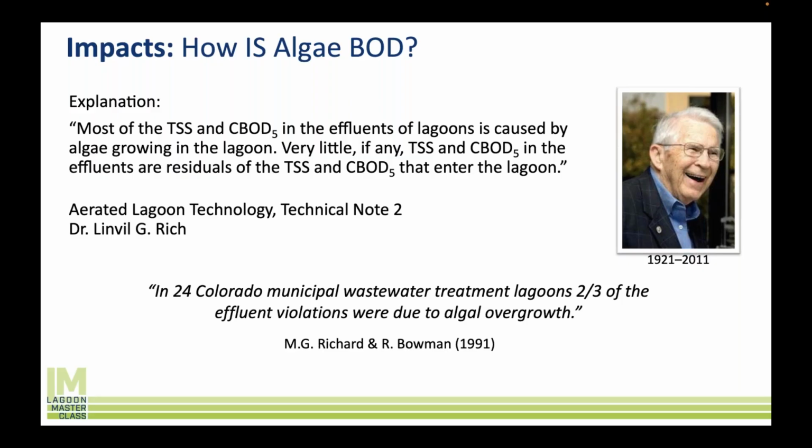So Dr. Linville Rich is sort of one of the godfathers of lagoon expertise, passed away in 2011, unfortunately, but did lots and lots of studies on lagoons. And we refer to his work a lot, and I actually refer to it in this presentation twice. And he came to this conclusion that most of our TSS BOD violations are a result of algae and not necessarily what's coming in from our collection system.